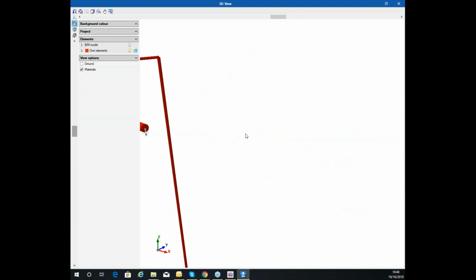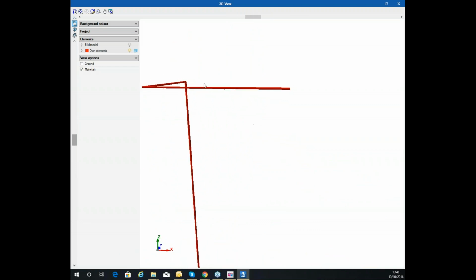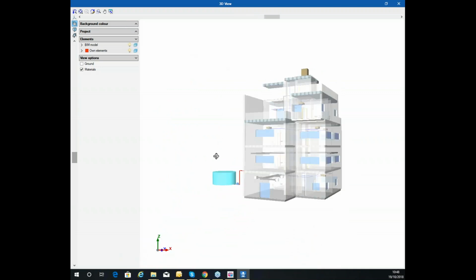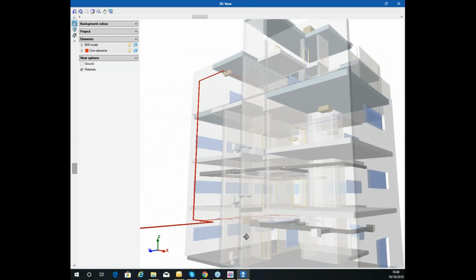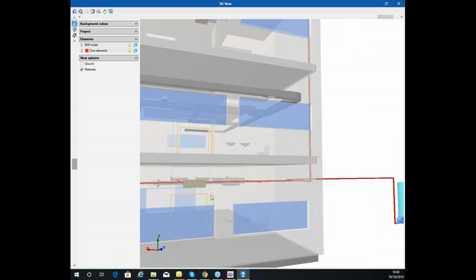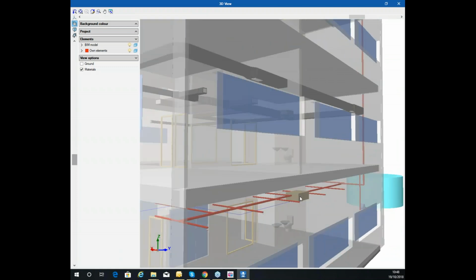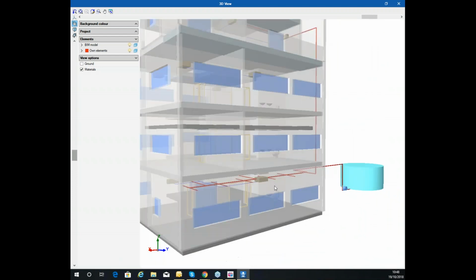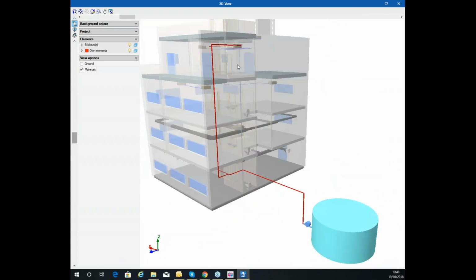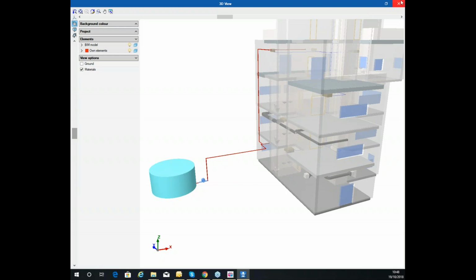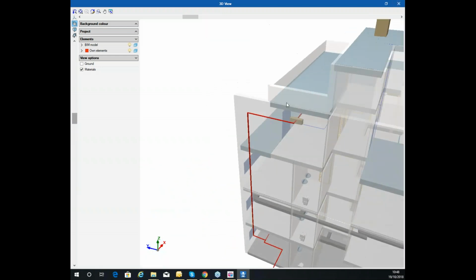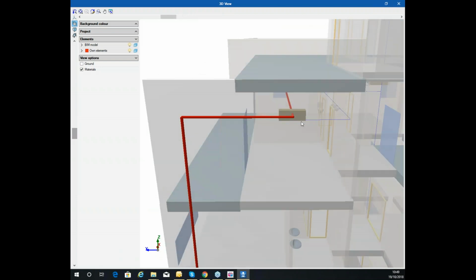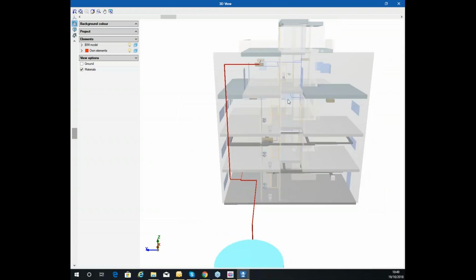Okay, this is the riser, up to another floor in order to complete this room. So as you can see, it's very simple to use. It's very user friendly, and here you can detect interferences between, for example, HVAC and this equipment clashing with the fire protection sprinkler network, which shouldn't happen, obviously. And you can detect and manage all your interferences in the design phase. It's very used. Okay, and in this case also other clashes, other interferences between this internal unit from the VRF, for example HVAC, and the pipes of the sprinkler network.